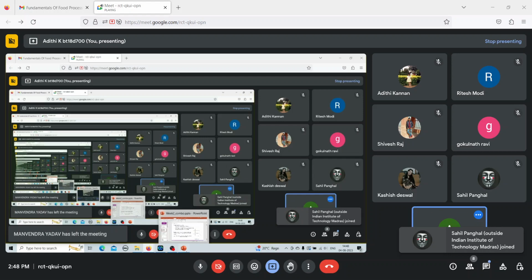This is because of the elastic nature of the fluid. Then even though you are maintaining a constant strain, you can see a decrease in the stress, which means that in a viscoelastic fluid, if you want to maintain a constant deformation, the amount of stress you need to apply keeps on decreasing with time. It gets easier to maintain that strain in a viscoelastic material.